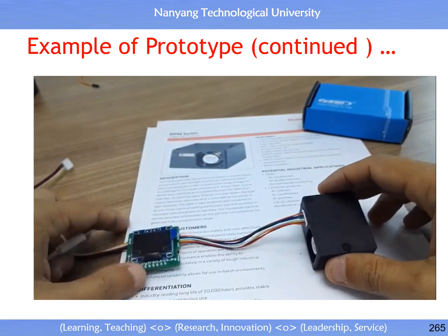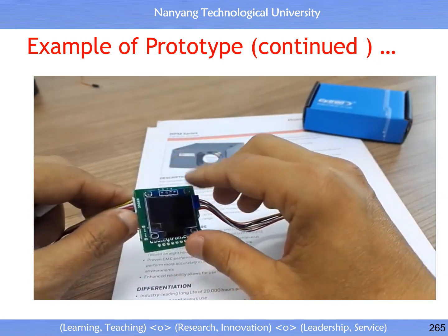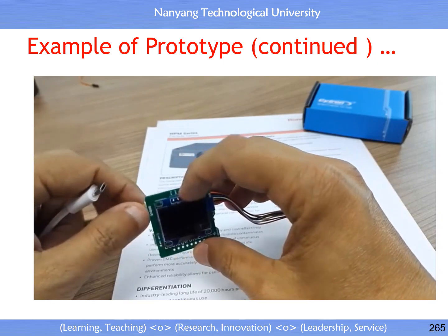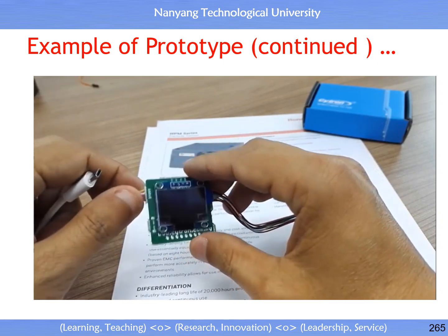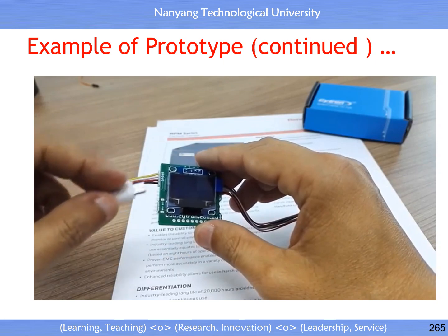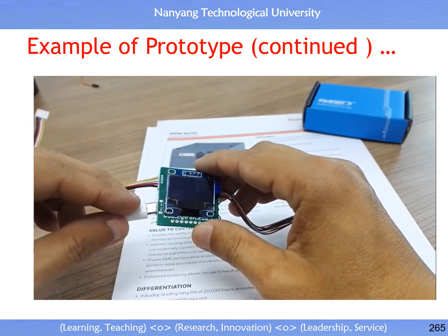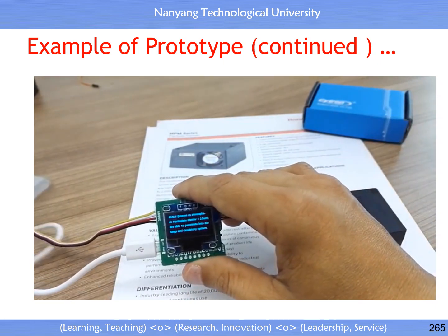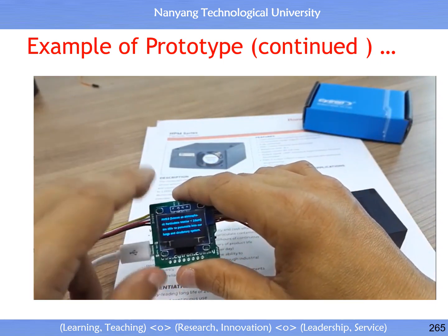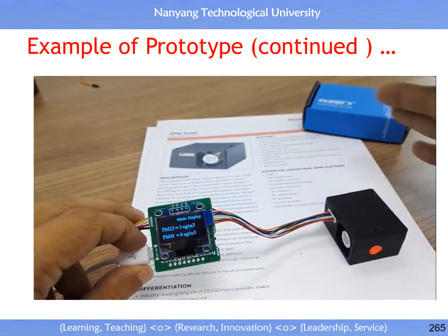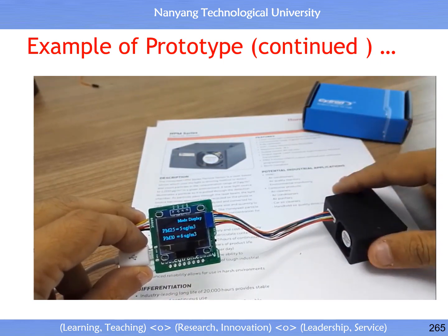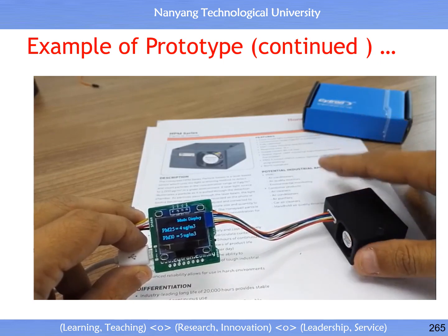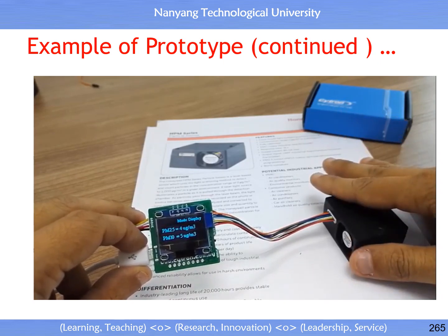Get started easily. You can get a separate OLED from our store. As you can see, just solder 4 pins to this breakout board and power this board using a micro B from, let's say, your power bank or your phone charger. So you'll actually power up the sensor right away. You might need to wait around 10 to 15 seconds before the reading is stable.